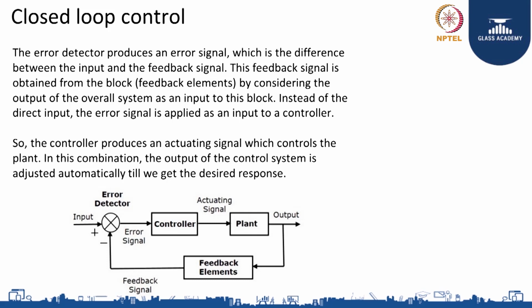It can also give a signal to blinds and increase the daylight coming from the windows and try to achieve the 500 lux. So basically, the controller gives the actuating signal, and then the system achieves a new state, and we measure whether our set point is being met or not. So this loop continues till we achieve the set point.